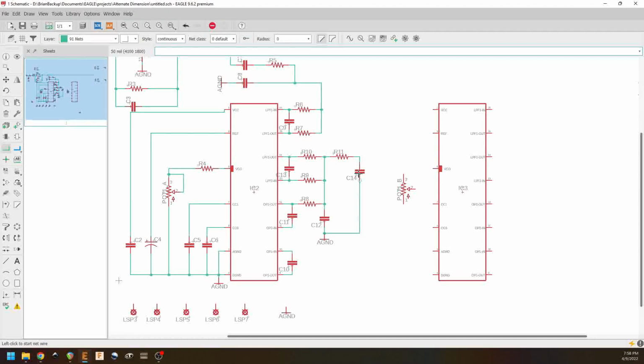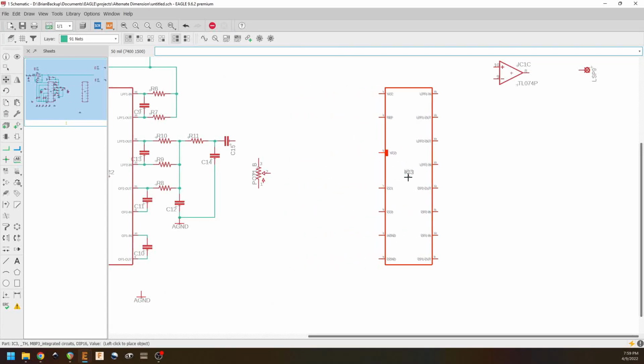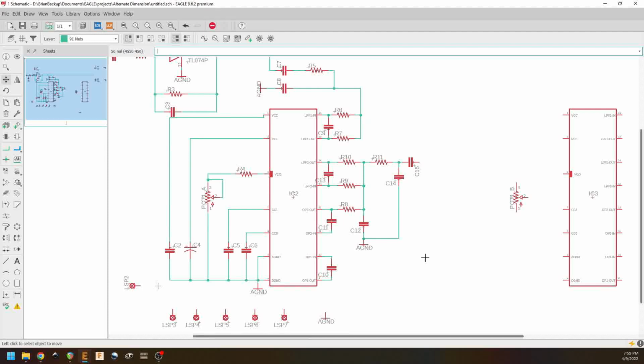And then we're going to put in a DC blocking capacitor before we send our signal anywhere else, so that any DC that might be riding on the output of this op amp gets filtered out, and we only have the AC portion of the signal. And obviously we are going to need to move this guy. But now we have a complete first delay stage. We'll need to put in some values in a little bit, but for right now, we just want to get the architecture all put together.